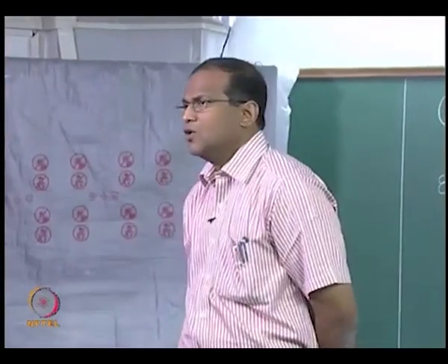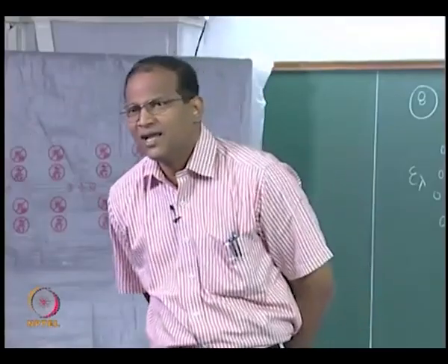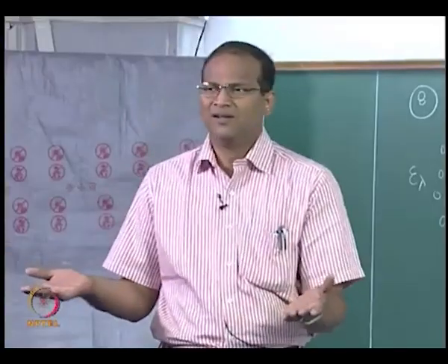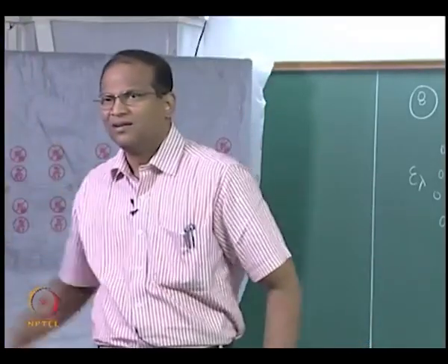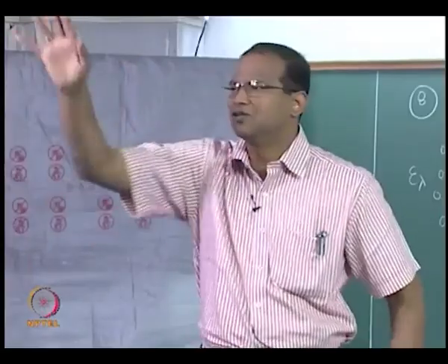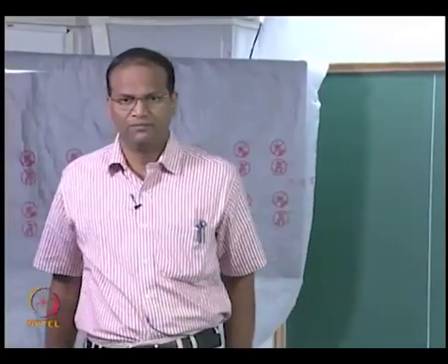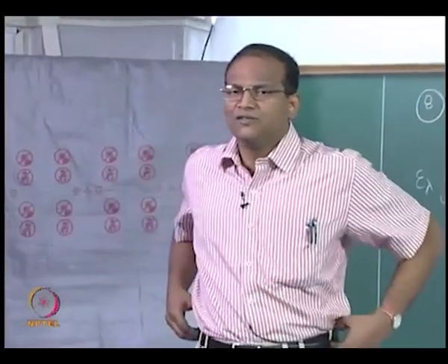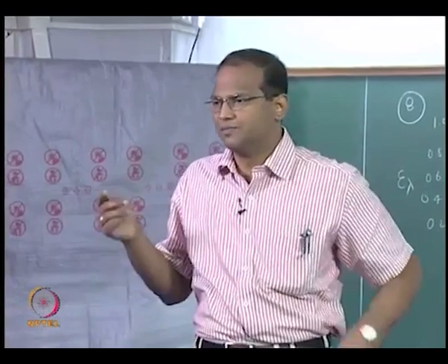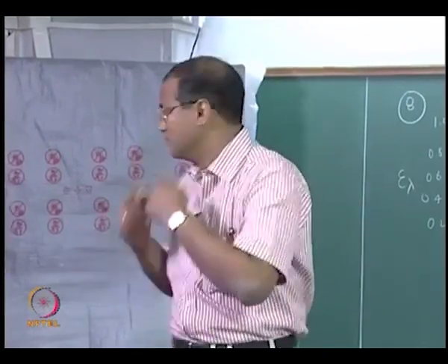Shall we start solving? So the story is from epsilon lambda you have to convert it to epsilon, and then you have to use the Stefan-Boltzmann law and look at the power consumption. Some critical data is not given, the area of the bulb, but needless to say the area of the tungsten bulb is the same as the area of the zirconia bulb, so you can cancel it. T is also the same, T infinity is the same. So the power consumption will be a direct ratio of the emissivities only. Then part C is you have to look at what is the radiation which is produced in the visible part of the spectrum.